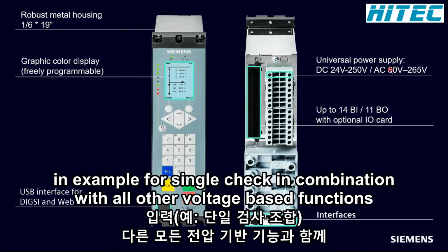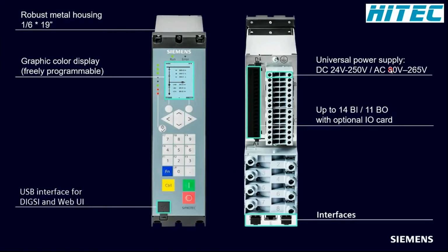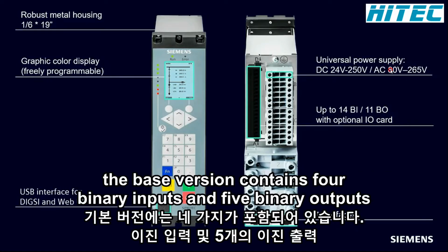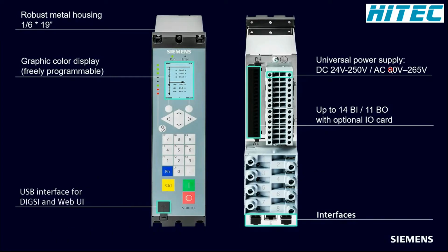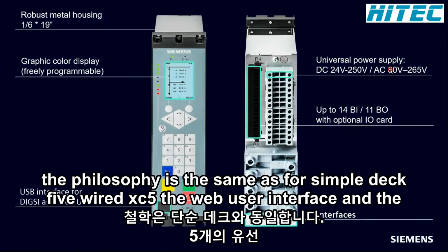for example for SIPROTEC in combination with all other voltage-based functions. The base version contains 4 binary inputs and 5 binary outputs. Including an additional I/O card, we can offer 14 binary inputs and 11 binary outputs. The philosophy is the same as for SIPROTEC 5.